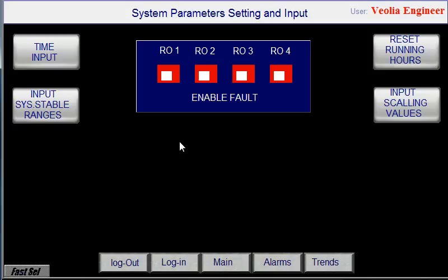My recommendation, if you are going to start the system for the commissioning purpose, is not to check this one, because if you enable the alarm, you will not be able to set the parameters for the flow control valve on the reject side and on the feed side. So keep this one unchecked and run the system. Once you set your parameters, which will be your pressure and the flow for the feed, for the reject and for the product, then you can come here and enable it.